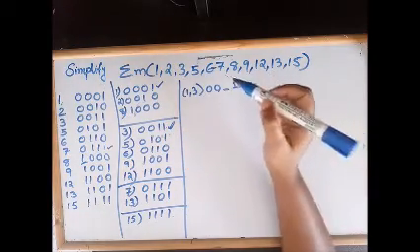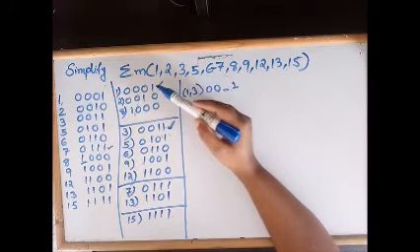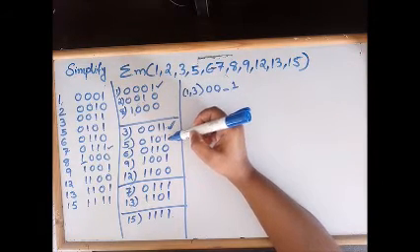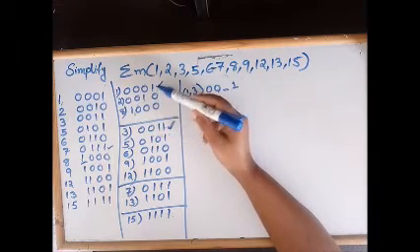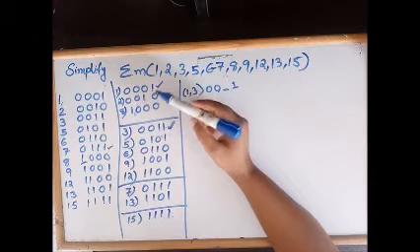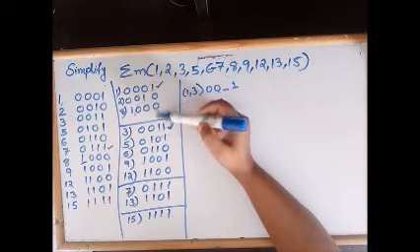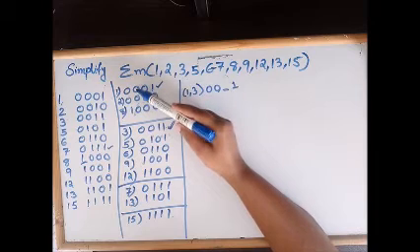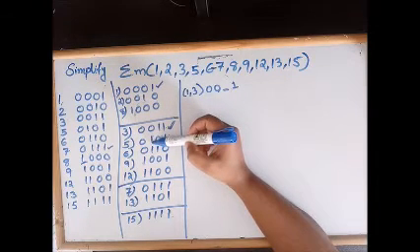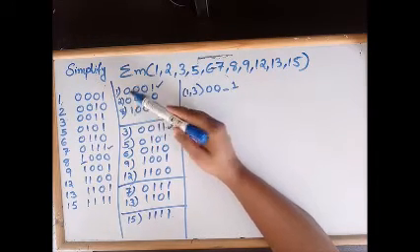Okay, then I need to combine what? Combine the first with the fifth element. So when we are trying to combine 1 and 5, what about the number of bit changes? So here 1 1 same, 0 0 same, and the next bit here it is 0, but here it is 1, so 1 bit change, and 0 0.